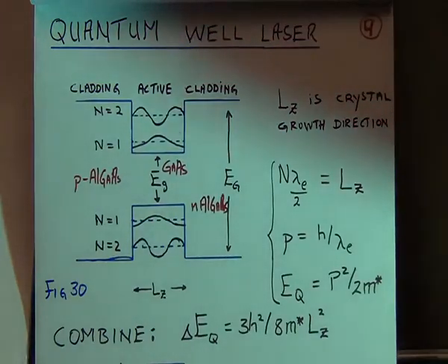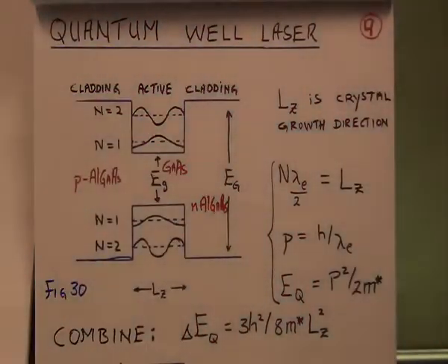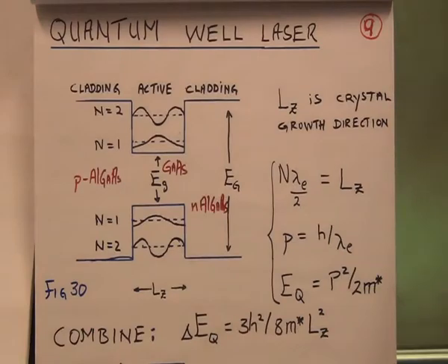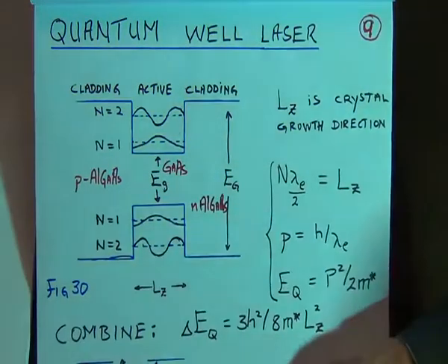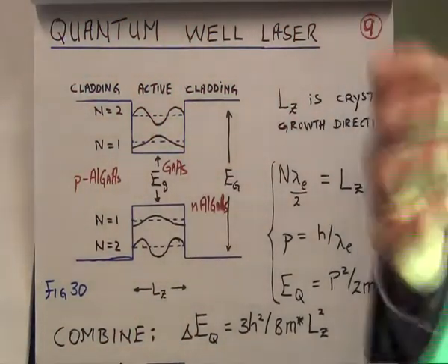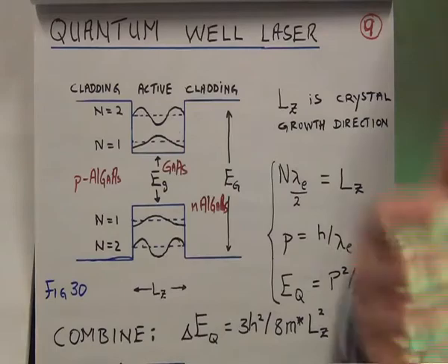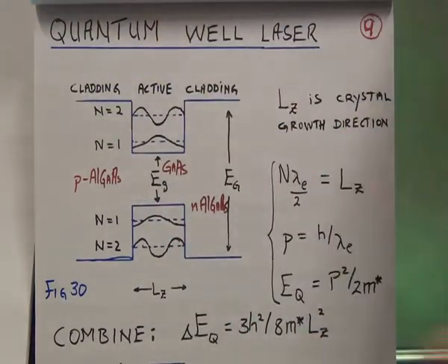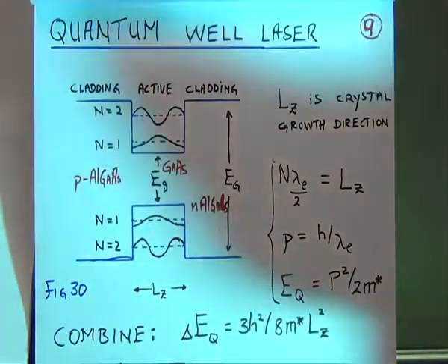Now, to make it thinner, it means you need to be able to grow in the deposition chamber layers of material which are only about 20 nanometers thick, 200 angstroms. So that's pushing deposition technology from the crystal growers and all that to its limits. But it can be done today.